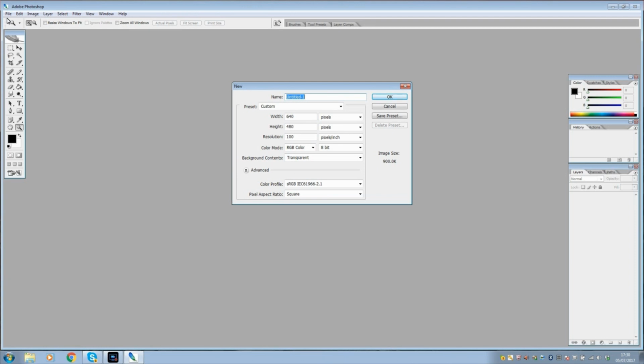Now combine that with another factor as well, and that is that we're going to be digging deep into the material. And as we dig deep into the material, two things are going to happen. Number one, the power is going to decrease because the energy density decreases because the beam is actually getting bigger and bigger and bigger because it's getting out of focus. Maybe the idea of having uniform power steps is not that bright after all. But hey, let's forget about these practical problems and just stick with the idea, shall we?